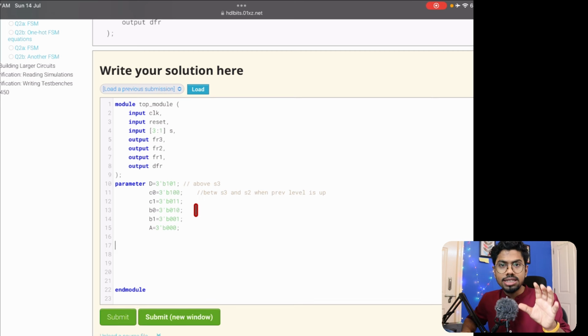And then the main thing, that is the combinational block for your next state. Again we need to define our next state. So first of all, state, and we will define it as a register of how many bits? 3 bits. Why 3 bits? Because our states are 6, so we need at least 3 bits.